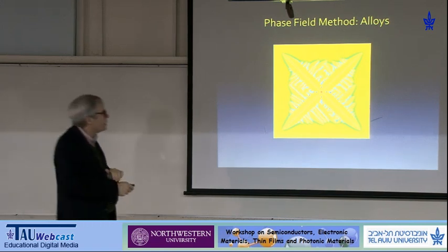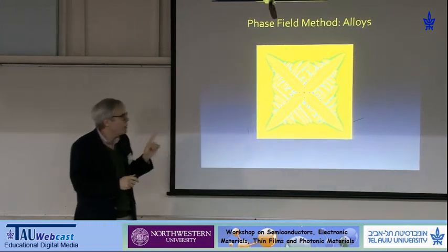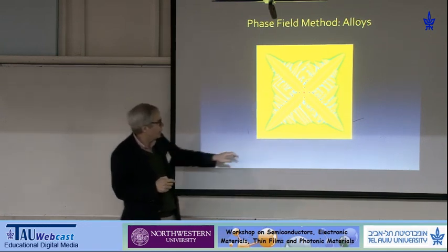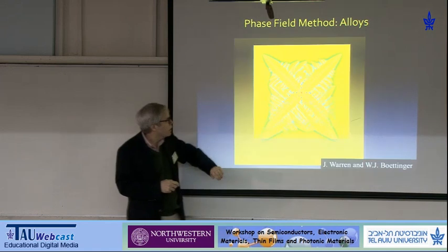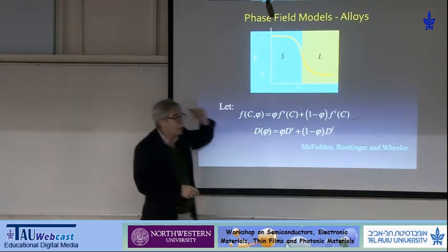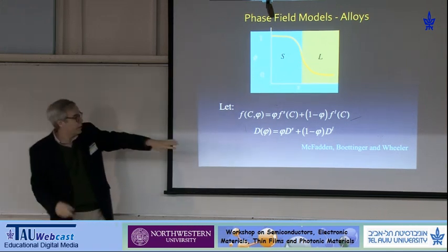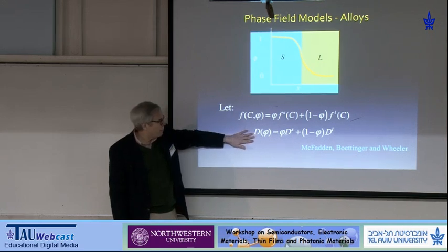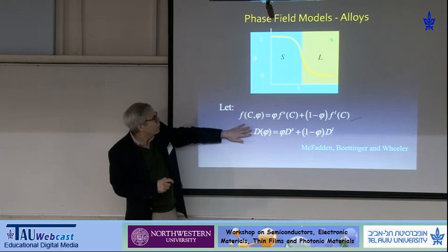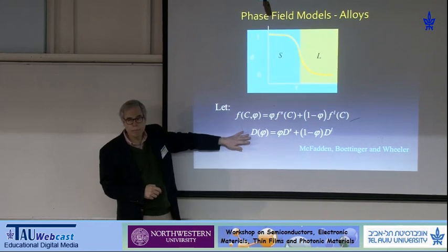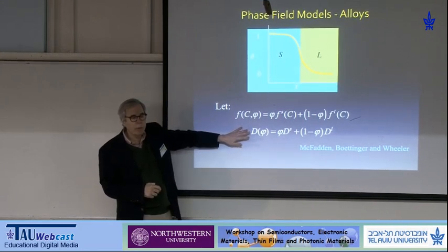And so this is the challenge with phase field methods. And the big problem, and this is a very subtle thing, the big problem that they were unaware of when they used this kind of model is that this reasonable assumption on how you interpolate from solid to liquid as you go through the interface gives you spurious terms in the diffusion equation. And actually, how you interpolate interfaces when you go from one to another in a phase field model is still an open question.